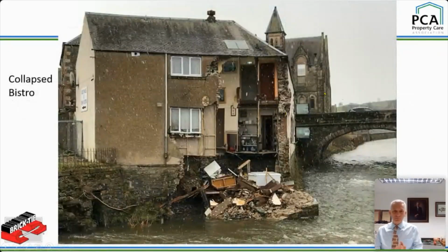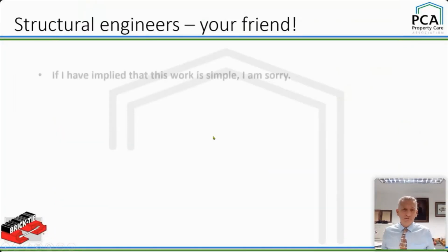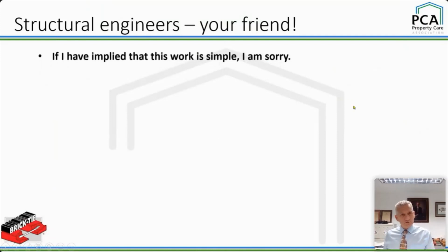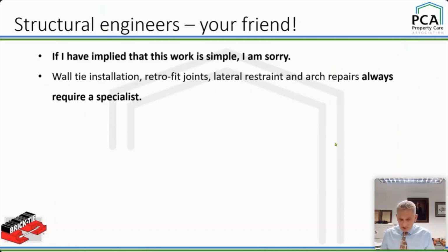That's it after the collapse. And you can see the collapse is nothing to do with lateral restraint. Absolutely nothing to do with lateral restraint. It's been undermined. We must stress this for you. Everybody, boys and girls, you all must remember this. If I've implied it's simple, the basics are, but it's not a simple thing. You need a specialist. Wall tie installation, retrofit, lateral restraint and arch repairs require a specialist.